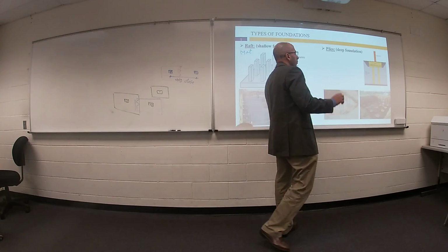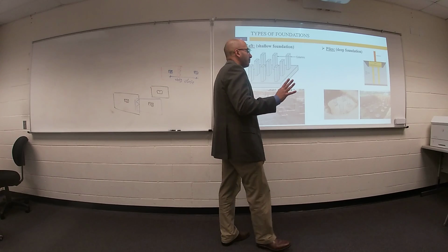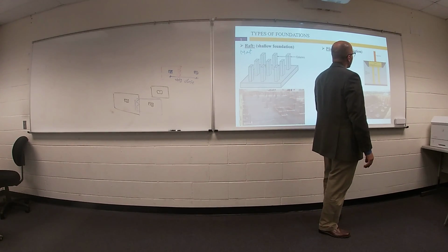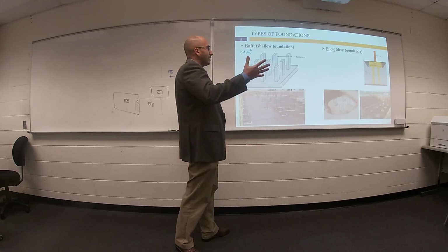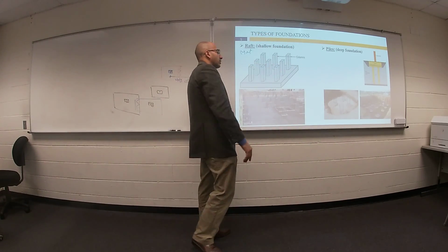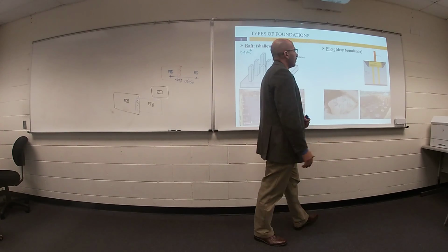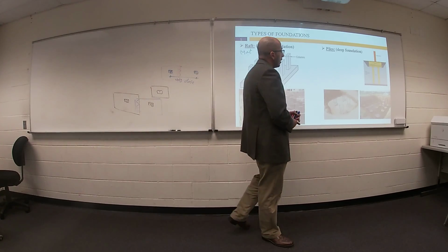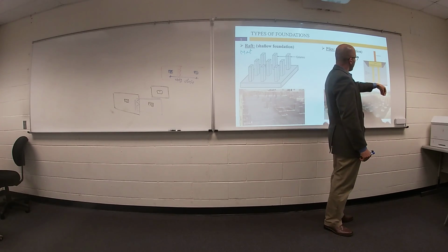The last one is called deep foundation. 100% of highway bridges are constructed using this type of foundation. For buildings, some 10%, 20%, 30%, based on how many floors you have, we use deep foundation piles, based on the type of soil. Piles means you have an embedded column in the soil.